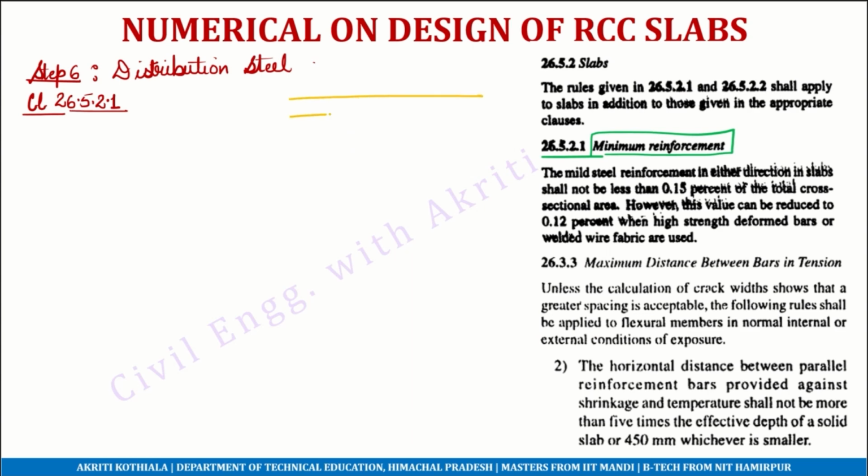Distribution steel is also known as temperature reinforcement or distribution reinforcement. So how do we provide distribution steel? It is the steel provided perpendicular to the main steel. So let's say the yellow steel which I am showing on the screen is your main steel. Then the steel provided perpendicular to this main steel will be known as distribution steel.